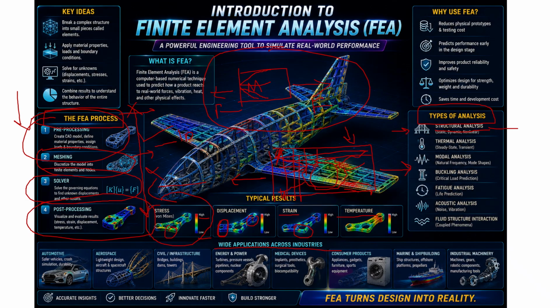Another is the thermal analysis. You can apply steady state heat or transient conditions. Then you can apply the heat and check how the part is going to behave under these thermal conditions. Then third is the modal analysis.